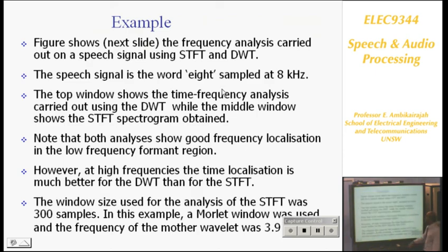So I'm going to show you an example, and that's the easiest way to do it. These two equations have been applied to a speech signal, and I'm going to show you how the short-time Fourier transform distorts some of the frequency information, and how the wavelet transform not only retains the frequency information but also retains the time information. That's why we call it time frequency analysis. Okay, let's look at the waveform.